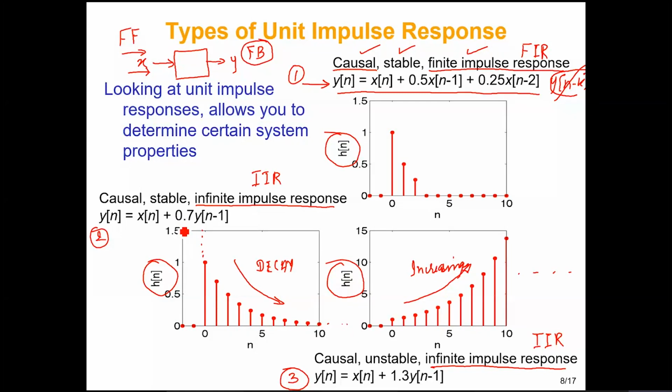So if you see here, this is your y of n minus 1, previous output, added here. So output with one delay will be added right here. This is your feedback term, a single feedback term being added to your feed forward term. So even if you have a single feedback term, in other words, a y of n minus something term, you will end up getting an IIR. We can have more than one also, y of n minus 2, y of n minus 3, but even if a single y of n minus any term is present, then you will end up getting an IIR.